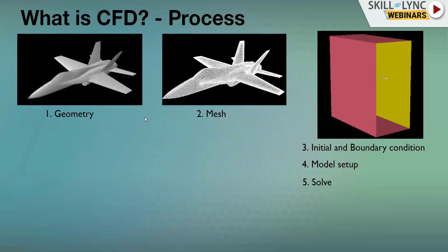We try to restrict the domain of interest, and for whatever the boundaries of the domain, we have to make some approximation and give values there. That approximation should be reasonable and should be able to capture the physics. Most of the time, if the CFD solution is not converging or has some issues, it could be a problem with the boundary conditions, or sometimes the meshes.